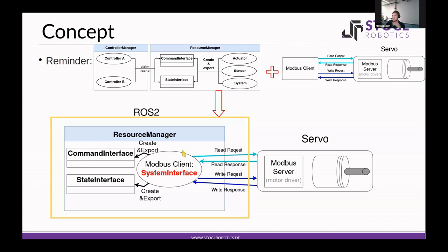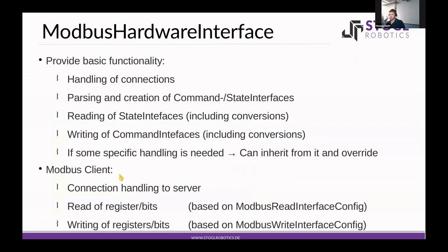The Modbus client, the system interface we created, initiates the connection when the hardware is activated, automatically deactivates the connection, and in every read or write step, the read request is sent to Modbus, and the values are then set in the state interface and published.